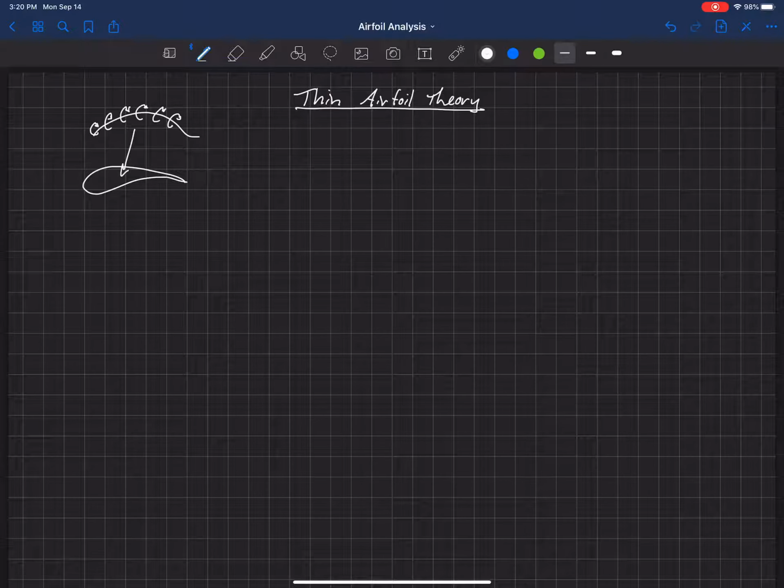And from experimental data, it shows that this is pretty accurate for airfoils that are less than about 12% thickness. And 12% is a fairly decent, a normal thickness that we would see on an airframe. So anyway, it turns out that this theory is actually rather accurate for many applications. Okay, so let's walk through some of the approximations here.